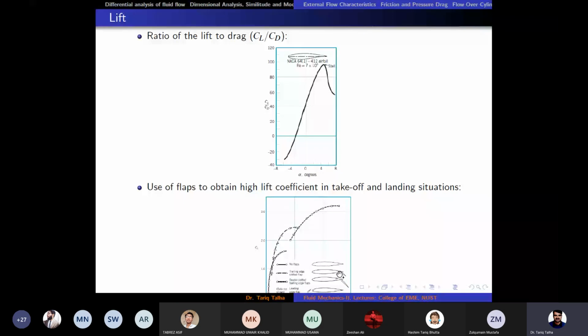But the consequence of putting the flaps more and more in the downward direction is that the drag force would also increase. But it would also come with an increase in lift, which we usually employ, because it is only a small portion on the trailing edge, so it would increase the CL value more as compared to CD.